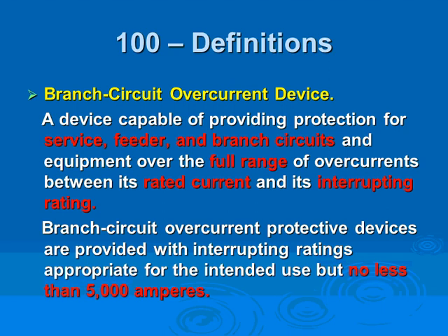When it comes to overcurrent protection devices, guys, there are 2 amp ratings for them. One of them is the continuous, typically continuous operation of the amps. 20 amps is a 20 amp. The load operation, 20 amp is a 20 amp, pull 20 amp out of it. And the second one is the interrupting operation. Now, interrupting operation, if you short circuit, the circuit breaker has an interrupting rating, which is 10K, 10,000 amps. This circuit breaker can handle that. If you put 11 in that circuit breaker, that could explode, or it could turn into a conductor, solidly bolted together, and it doesn't interrupt.